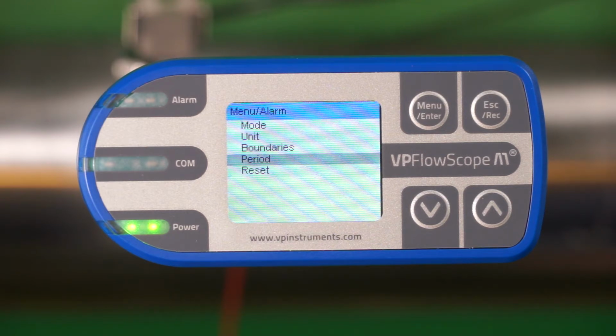These settings are saved, so we have set that when the alarm conditions of minimum 200 cubic meters per hour and maximum of 1000 cubic meters per hour are met for 5 seconds, then an alarm will be activated. After 10 seconds of active alarm, the hold period is reset. That means that a new alarm is given after the complete hold period of 5 seconds again.